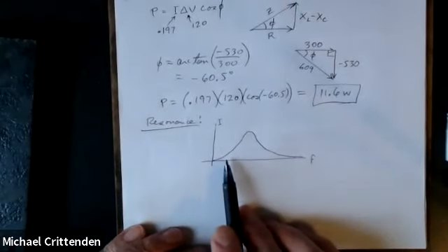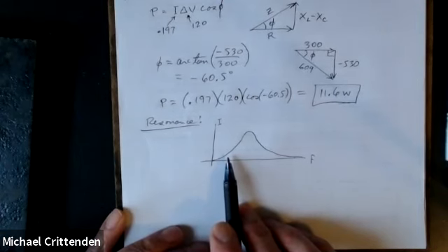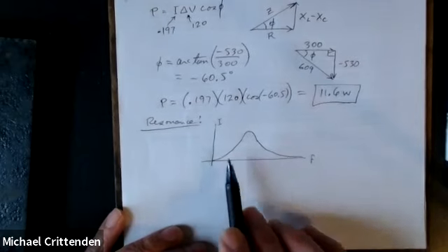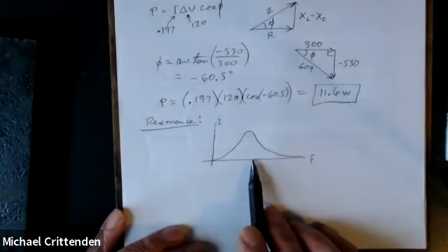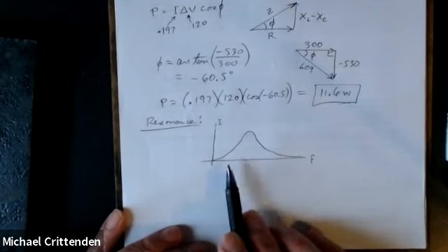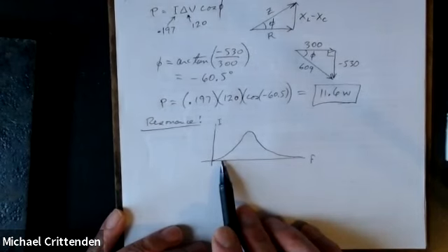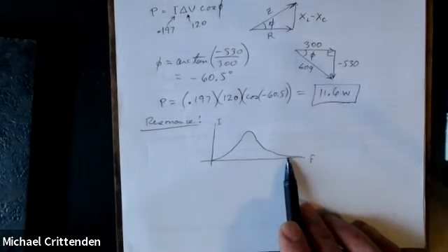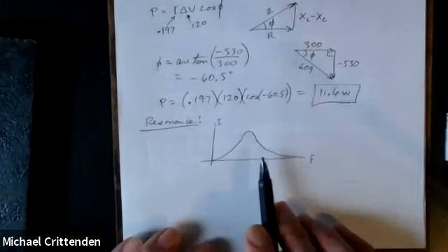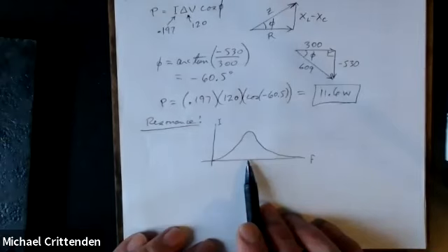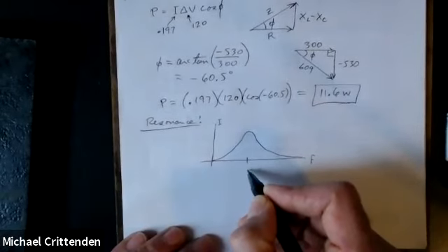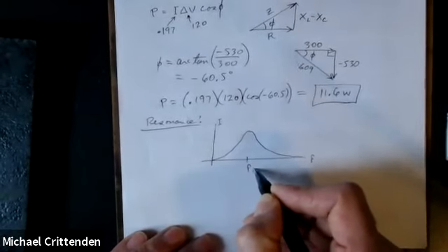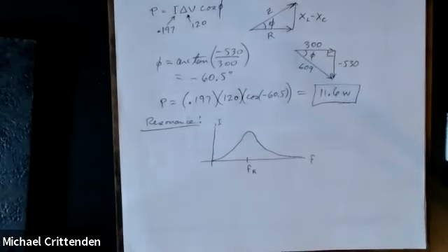So what's going on here is, like many things in life, it's like the story of Goldilocks and the 3 bears. This frequency is too small. This frequency is too big, but this frequency is just right. Low frequencies don't want to go through the capacitor, as I explained earlier. High frequencies don't want to go through the inductor. Somewhere in between, the reactances cancel each other out, and that is the resonant frequency. F for frequency, R subscript for resonant. Okay.